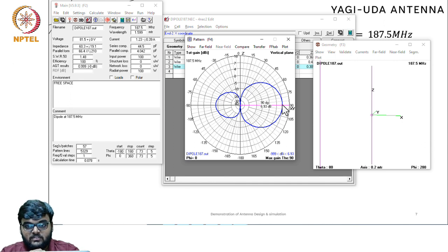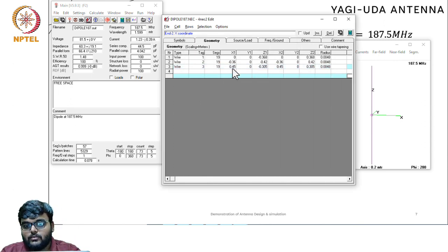So gain improved. Let's go to 0.42 and see what happens. If you go beyond, meaning very much less than 0.42, you will come into the quarter wavelength range. Then the beam inversion on the other side will happen, and the beam will become some kind of a mess. So we will see that also. Okay, so let's go to 0.42.